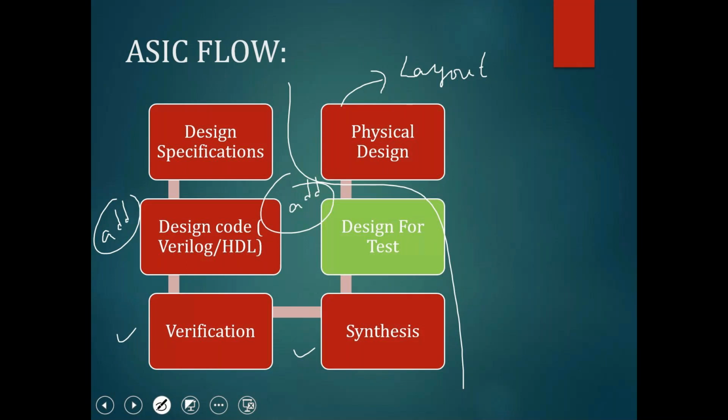So there'll be a separate team called the physical design team, also called the backend team. What they're going to do is the layout of the chip. They're going to take all the circuits we have and do the layout of the chip. Once the physical design has done the layout, it's a multi-process. The layout is a multiple process. It's not a single step. They have multiple sub steps, I would say, like floor plan, placement, routing, and different things. So it's a very lengthy process.